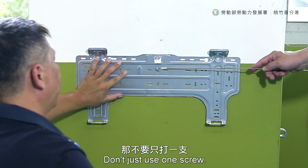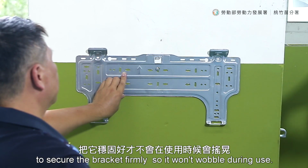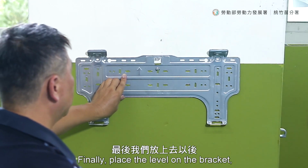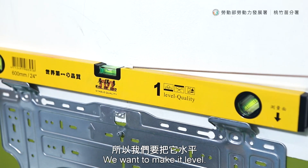Don't just use one screw. You should use around 5 to 6 screws to secure the bracket firmly so it won't wobble during use. Finally, place a level on the bracket and make sure it's level. We want to make it level.